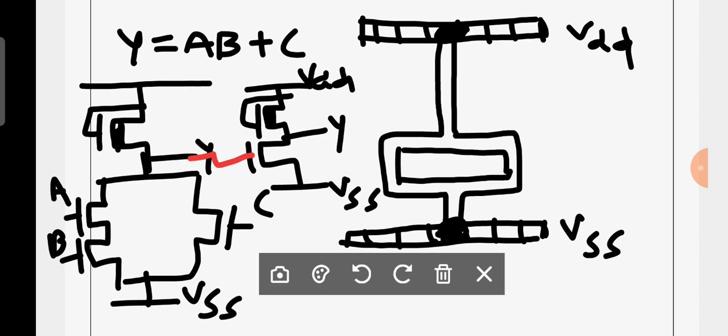Okay, now you can observe the depletion mode as it is. Then you have to draw a depletion mode transistor as it is, and it is what? Polysilicon, absolutely. And there is a contact here. It should not cross, that is very important. There is a contact and there is an implant here.